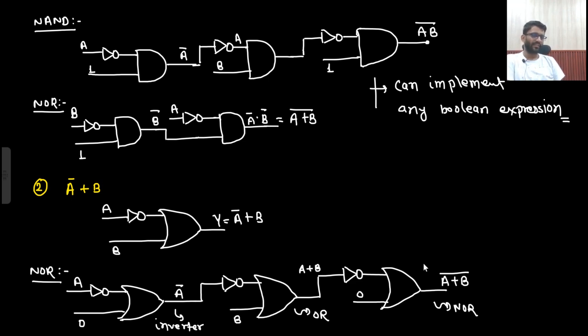So these are the examples. So if you think that you need 3 gates, then you are thinking wrong. You need only 2 gates. Because in your chip, in your IC, there will be plus 5 available. There will be ground available. So you will always have 0 and 1 with you. If you are having 0 and 1 with you, you can implement any kind of Boolean expression. Okay, so this was a very, very important point. Very, very conceptual point.